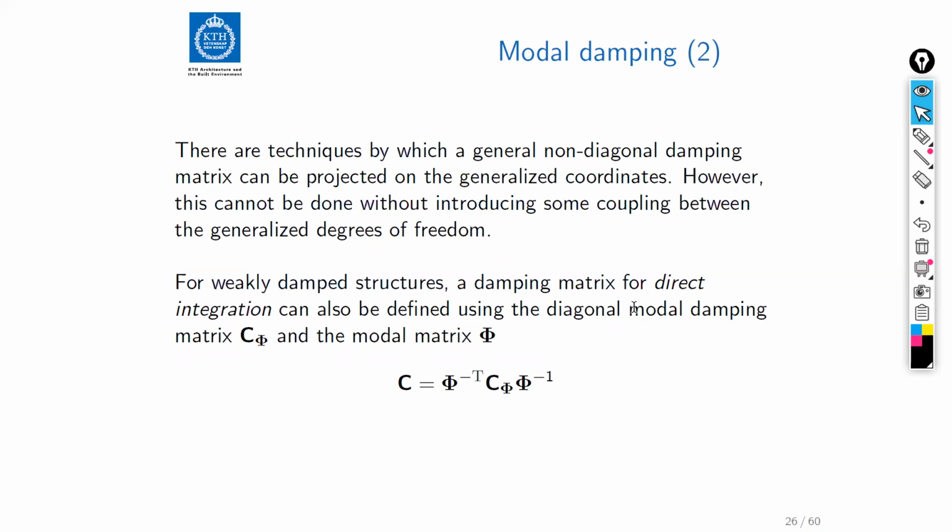Like for an example, if we are doing a dynamic analysis of a railway bridge, according to the Eurocodes, if it's a steel bridge, perhaps we are forced by the design code to use a damping ratio of 0.5% on all modes of vibration.